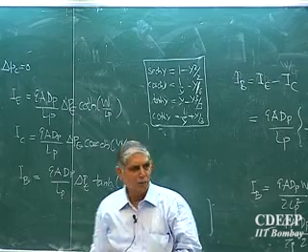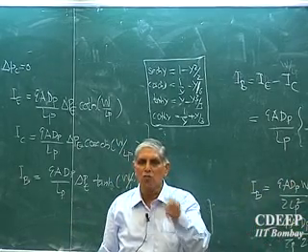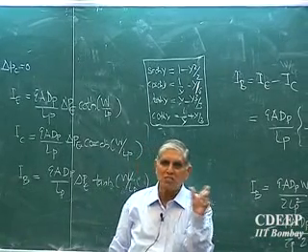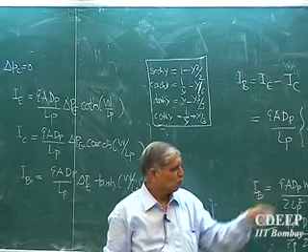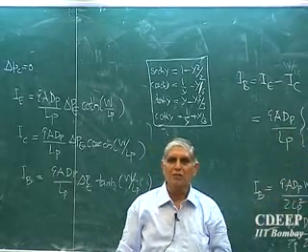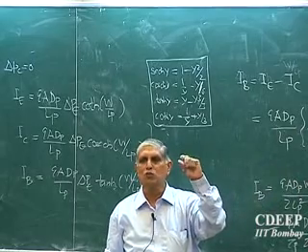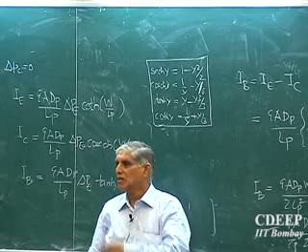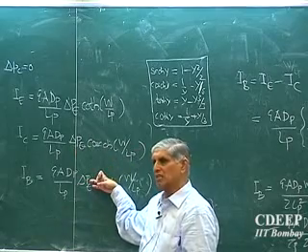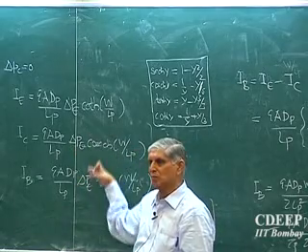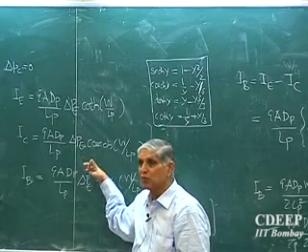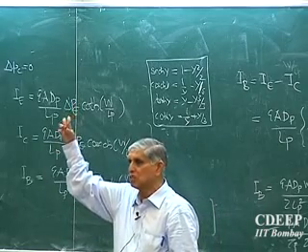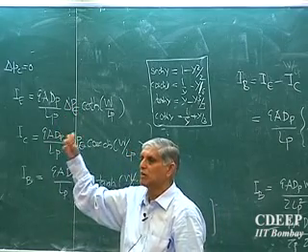Is that clear? I am trying to give you all this because in solving many problems, W will be given, taus will be given. So you know how much W by LP is to start with. So you don't have to rewrite all terms every time and figure out that the second or fourth terms are so small they are not even getting subtracted or added. We verified that if that happens, these statements can be used here. Is that clear? Please verify this condition that W by LP is smaller than 1 and delta PC is 0, that is VCB is sufficiently large, minus 5 volt, 10 volt.